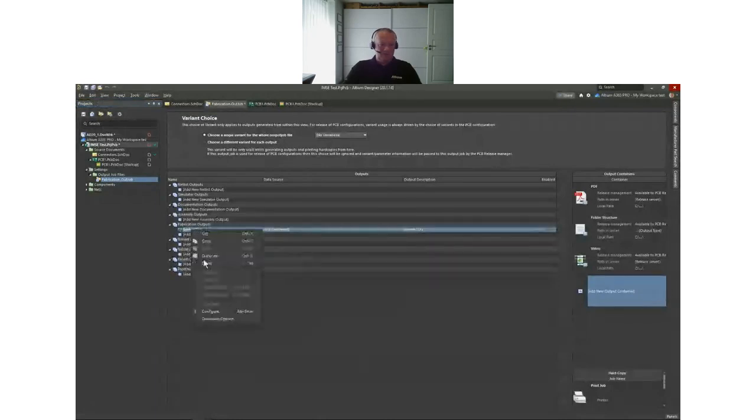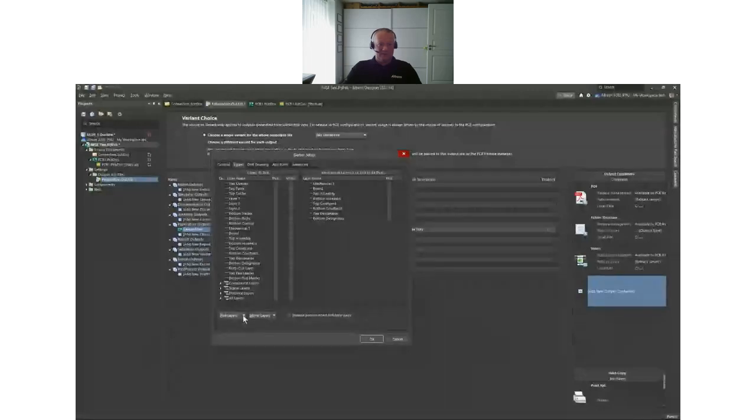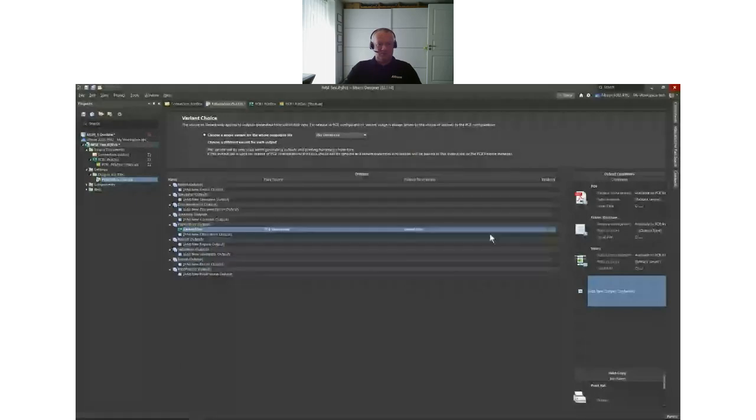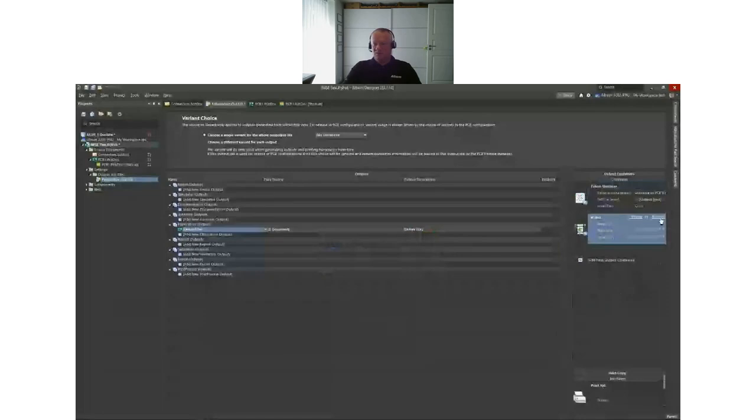And let's configure this one here. So it's okay to be in inches, and the 2.5 is definitely okay. So let's go for layers. And in this case, I will plot the used ones, so it will plot these layers for me. This is okay. I need some place to store this one here. So I don't need the PDF. Let's remove this one. And also not the video. But I need some kind of folder structure to put it in. So let's call this Gerber.